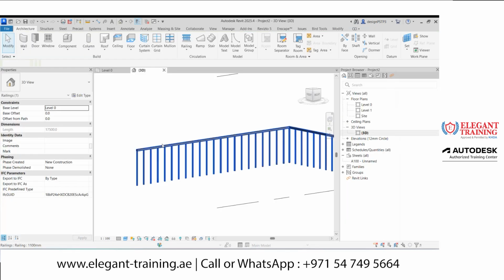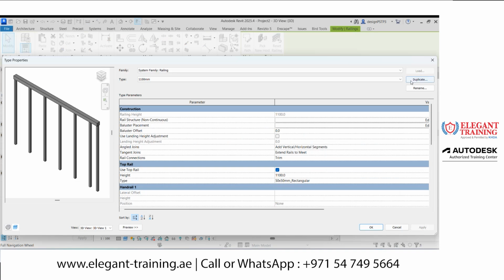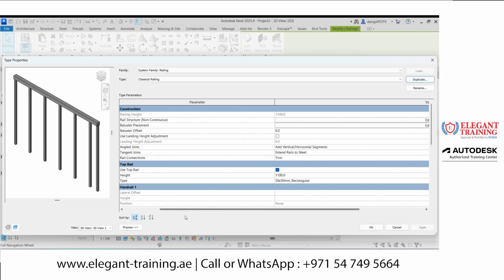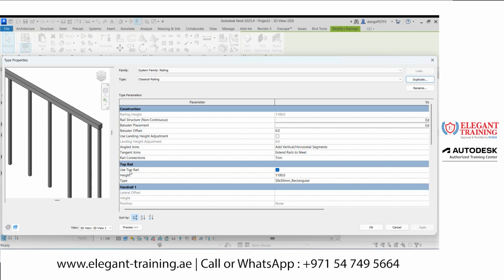So the first thing you need to do is go to Edit Type, take Duplicate, and I will just name this one Classical Railing. By default, here you can see the top rail. If you want to edit only this one, then I need to edit in the top rail. The top rail height is given as 1100, so let it be that way.